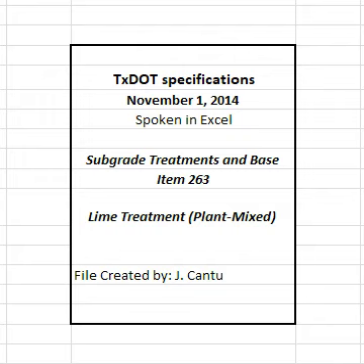Construct vertical joints between segmented areas of lime-treated base. The vertical face may be created by using a header or by cutting back the face to approximately vertical. Place successive base courses using the same methods as the first course. Offset construction joints by at least 6 inches.